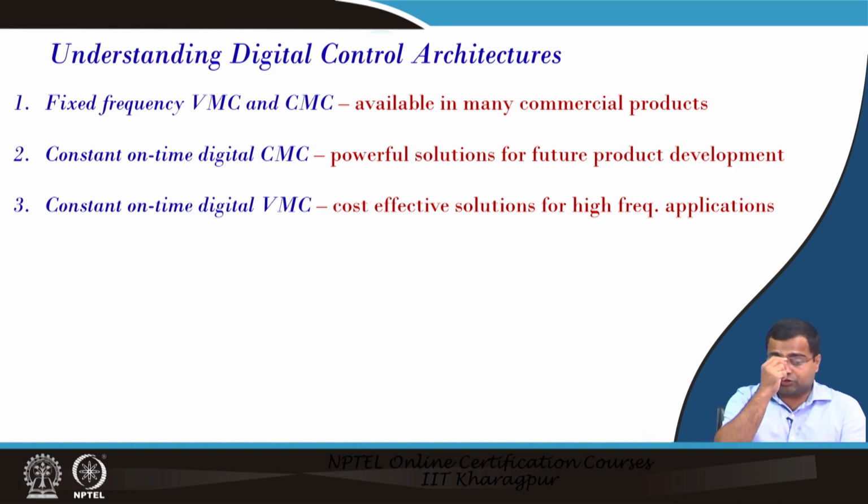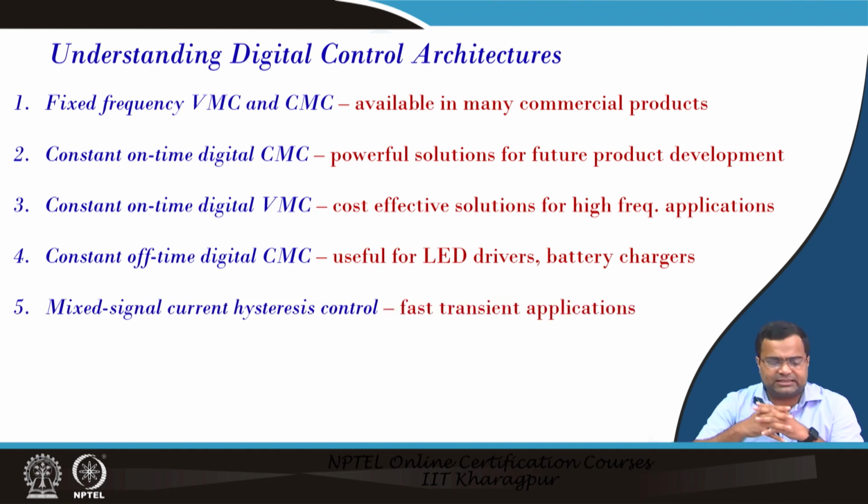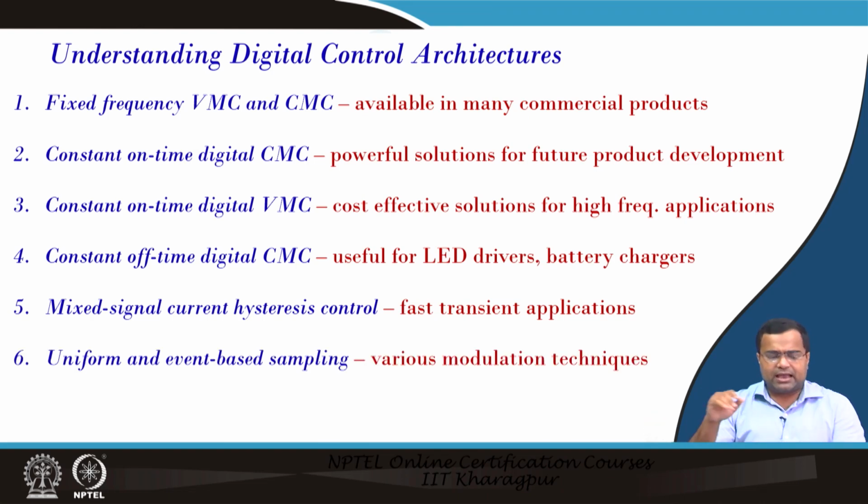Current mode control is also very useful for multi-phase and other applications where we need precise current regulation. Then constant off-time digital current mode control is also a very powerful solution for LED driving and battery charging applications. Then we have discussed mixed signal hysteresis control, which can achieve very fast transient response, and we have also learned uniform and event based sampling techniques for various modulation techniques.